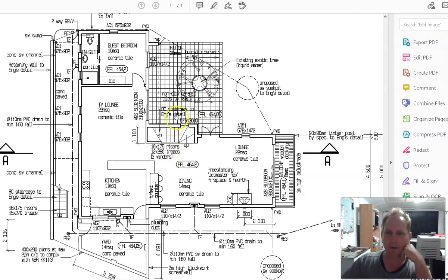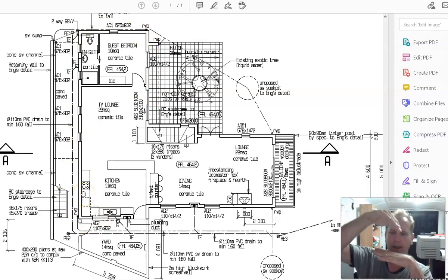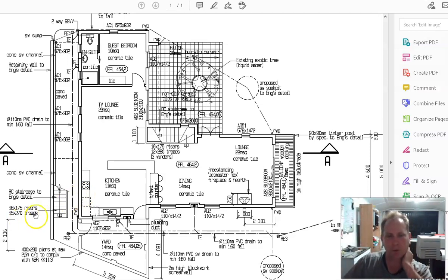Line weights, people. Hatching, thin line weights. So you've got hatching here, hatching here. If the entire house is new, you don't need to hatch the walls in. You know they're hatching for a wall. It's a big gap, a diagonal, a small gap, a diagonal, a big gap, a diagonal. You don't have to, because everything is new. It's only when there's adds and alts that you need to do that. This is wrong. I don't like a UP at the beginning of the stairs.